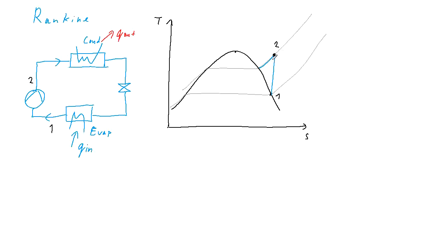So as you can see, we end up with the compression, at least in most of the cases, in the region of such superheated vapors. So it's the superheating, then condensing, and then eventually also, based on the ambient temperature, we can get the working fluid slightly subcooled.